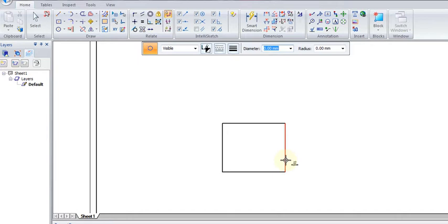the cursor has a small image to the bottom right, and it changes depending on where we are. We talked about this briefly before. These are the IntelliSketch constraints that we had talked about, and we want to make the circle tangent at the center of this rectangle. So we wait until we get to the midpoint indicator, we left click, and then we start moving outwards. You see that the circle again is attached to the cursor. So let's take it out a bit, and for the diameter of the circle we want it to be 80 millimeters.